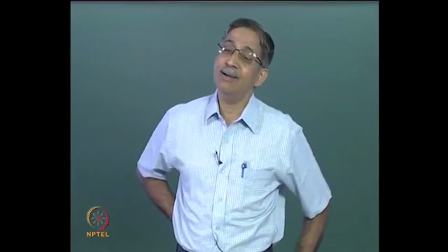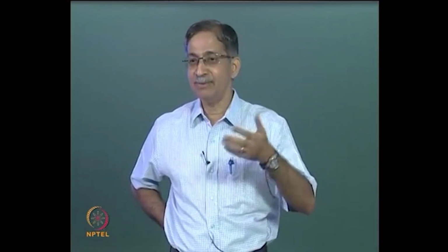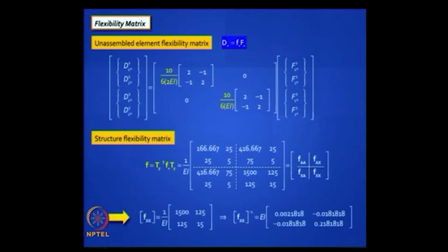Now which is the one you need to invert here? In stiffness method we always looked at the top left hand corner, that was KAA, but in flexibility, because everything is upside down, you have to look at the bottom right hand corner, that is Fxx. Is it clear? So that is 2 by 2 because your degree of static indeterminacy was 2. Take it out, invert it also, be ready. Inverting a 2 by 2 matrix is very easy. You are now ready to handle any loads.